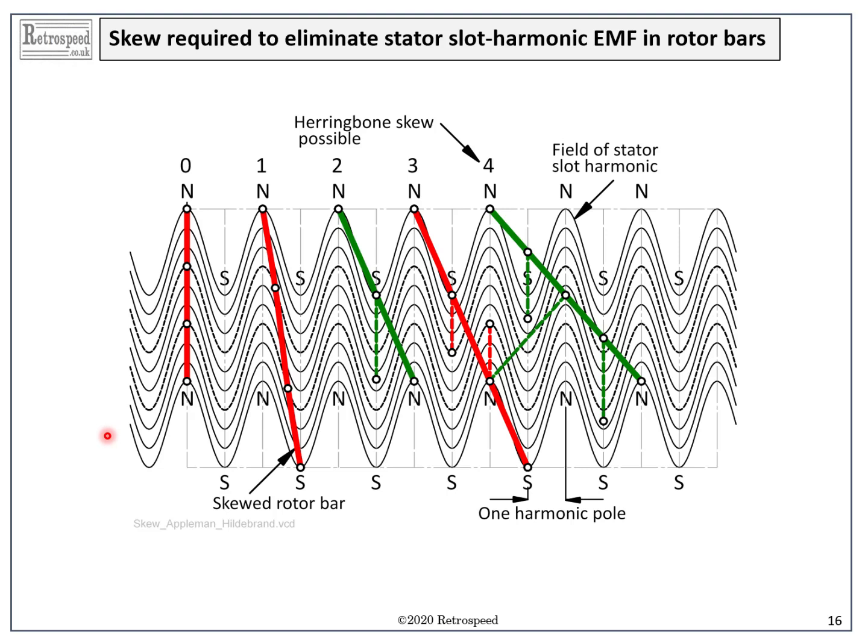This indicates one traditional strategy, which is to choose the slot combination very carefully, so that the only troublesome harmonic flux waves are the ones associated with the step harmonics, in this case the 23rd and the 25th, and to use skew to quell those. 2 pole pitches of the 23rd harmonic would be 15.65 degrees, which is 1.04 stator slot pitches, and 4 pole pitches would be 31.3 degrees. We would certainly see that on the rotor, and sometimes we do see it.